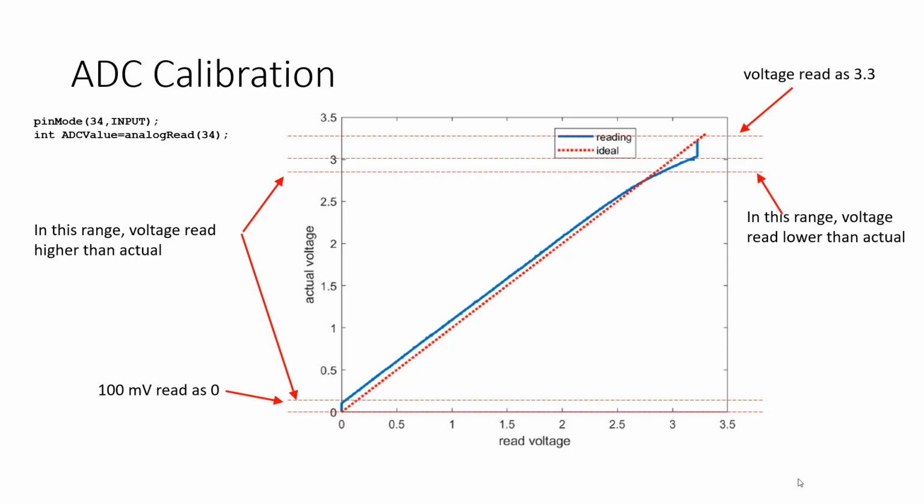And then we're going to go through this algorithm that's going to sweep the power supply output and collect data on the ADC in order to build up a calibration model. And then we're going to put it into a mode where it's just reading. When you do your demo, we're going to go up and manually change the power supply and ensure that whatever the ESP32 is printing is a reasonably close approximation of what the ADC is putting out.